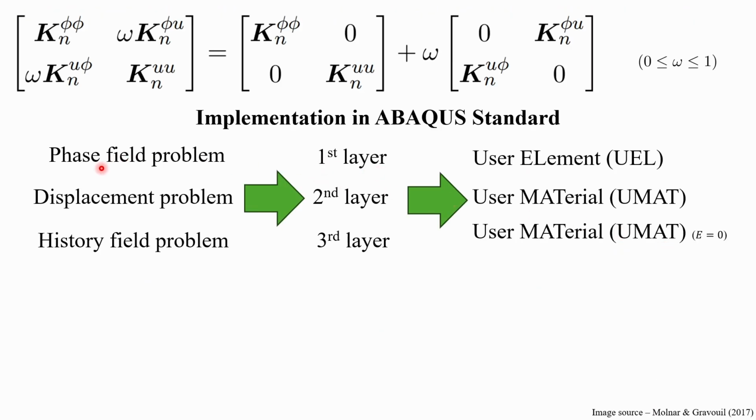The first layer, or the phase field layer, has to be depicted. When you want to solve something in the software Abaqus, if it does not fit the predefined list of finite elements given in the software, you will have to define your own user element. Okay. So this phase field layer, or the phase field element, is not a standard element in Abaqus.